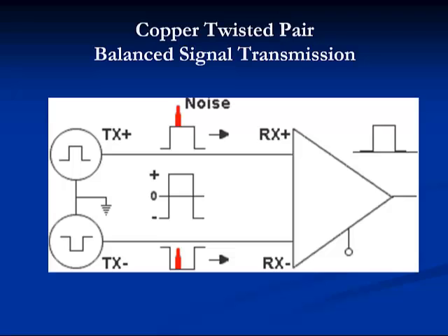Capacitance unbalance is also related to dimensions, but to the insulation surrounding the conductor. If the insulation is thicker on one conductor than on the other, then capacitance unbalance occurs. Or if the manufacturing process is not well controlled and the conductor is not perfectly centered, like a bullseye in the insulation, then capacitance unbalance will exist. Both these noise sources are usually kept well under control by the manufacturer and are relatively minor compared to crosstalk.